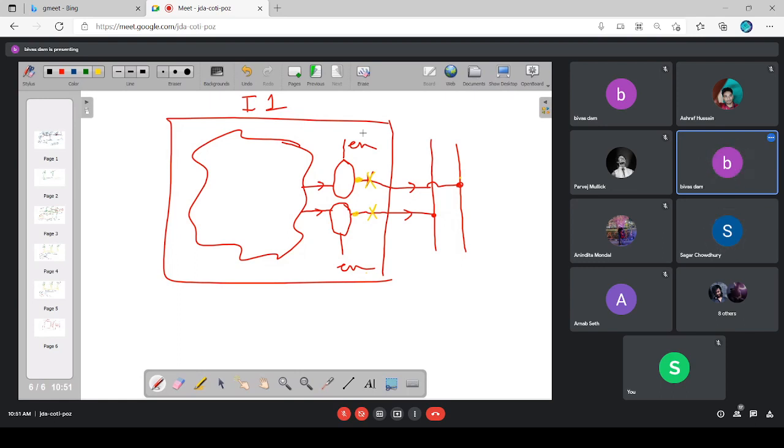If there is any confusion. Sir, tri-stated data, does that mean the decode is done inside the IC itself? Either internal to the device there is one address decoder, or externally I have an address decoder whose enable outputs go to individual devices. If the enable is by F2, here we have F0, F1, F2, F3. So this F2 will come here.